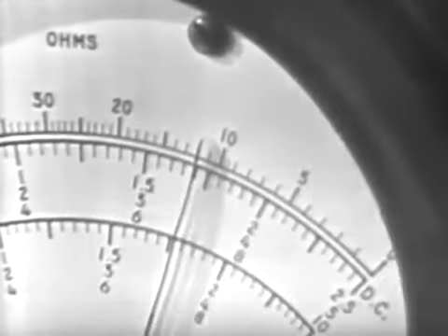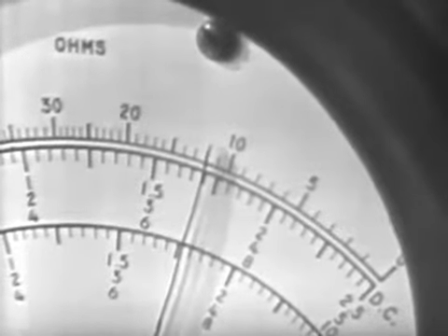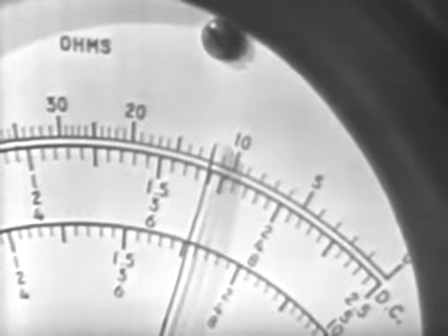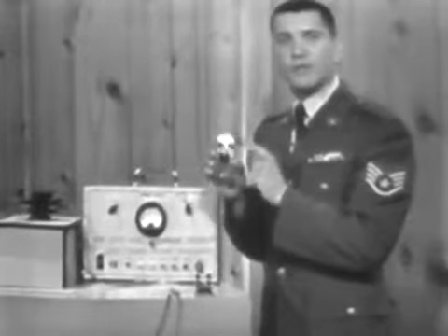We'll take a look at the meter now. We'll see that the resistance of this winding is only 12 ohms. But we've already pointed out the normal resistance of the 300 turns winding is 20 ohms. Thus, we can conclude that some of the windings or turns of this 300 turns winding must be shorted. Well, as a matter of fact, I've already figured it out, and approximately 70 turns of this 300 turn winding are indeed shorted. Now we see then that for a shorted transformer winding, the ohm meter will indicate a resistance less than the normal resistance of the winding. Now, of course, the greater the number of turns shorted, the greater the decrease in the resistance of the winding.